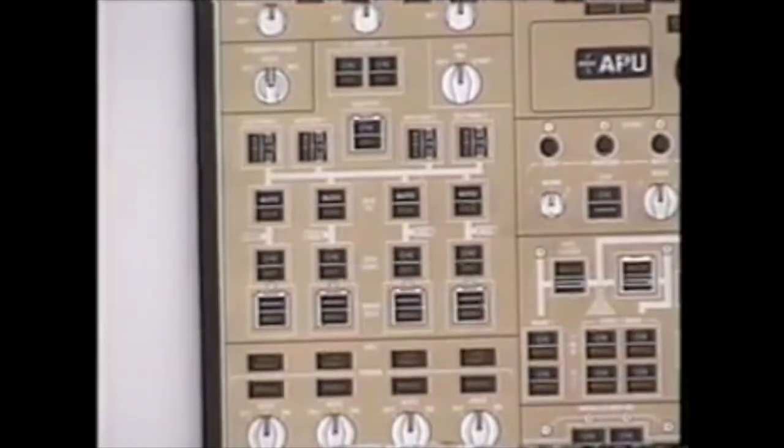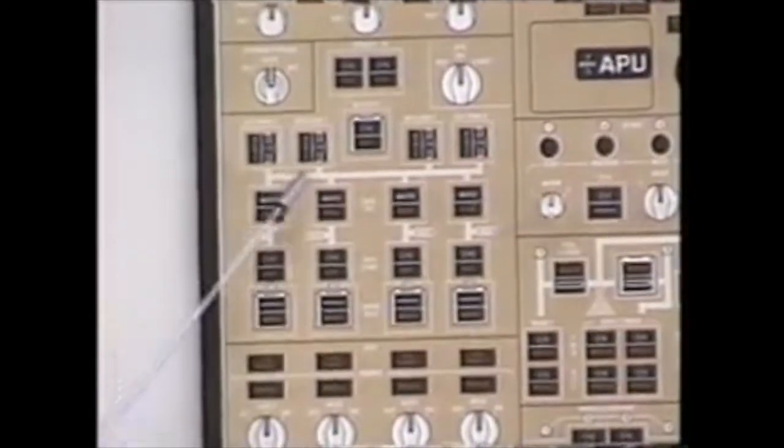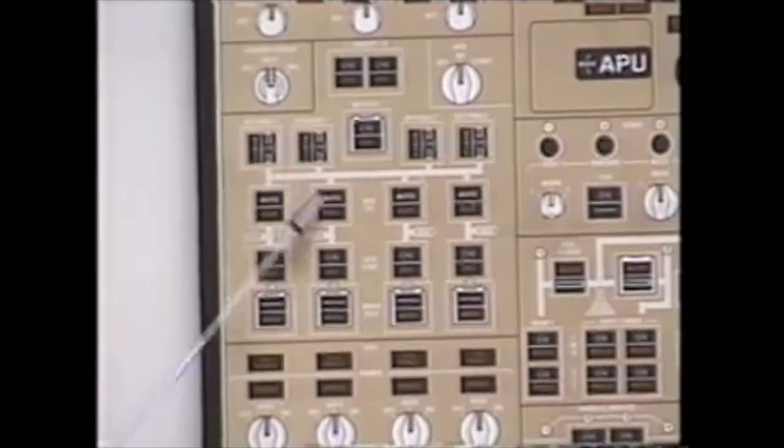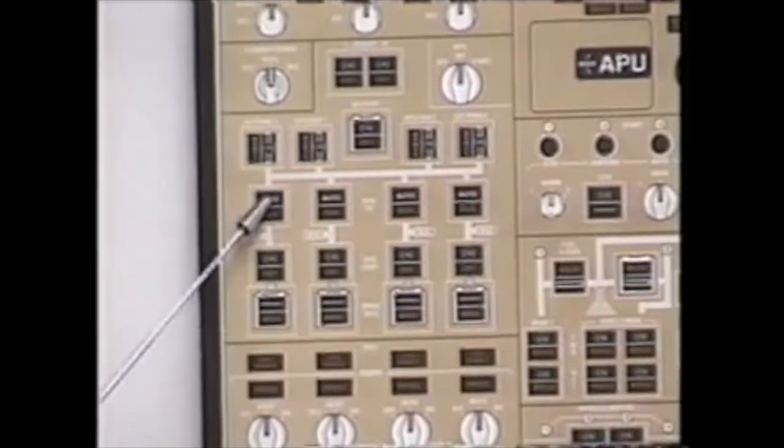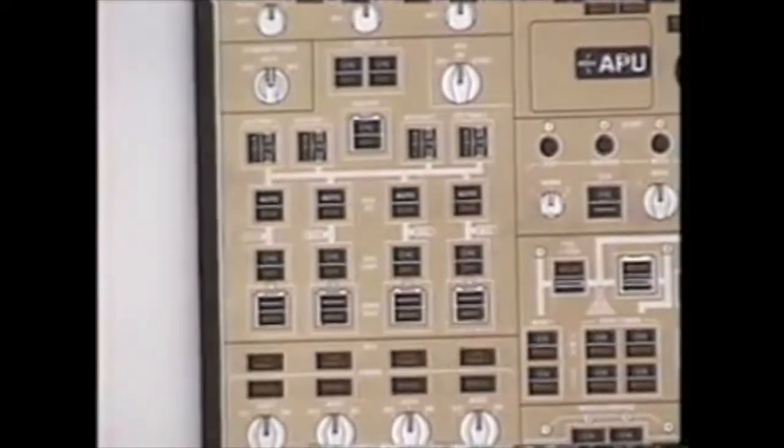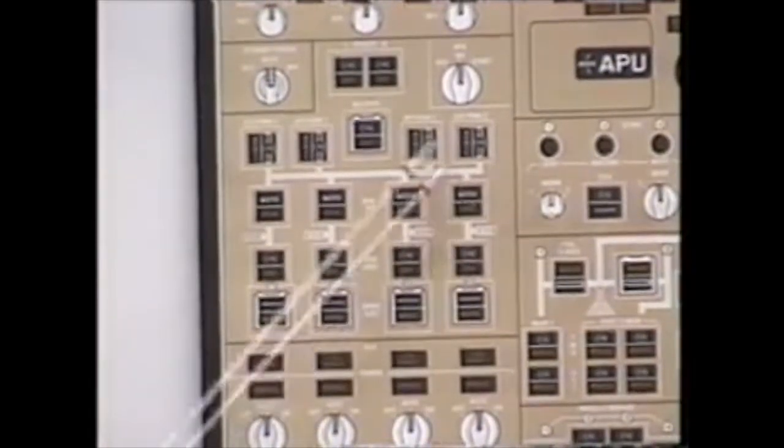Bus tie switches, auto and isolated. The airplane has the ability to isolate an AC or a DC bus and tell you about it on a primary ICAS. However, if you physically reach up and isolate a bus tie, you are opening both the AC and the DC buses. During a LAND 3 situation, the airplane will automatically isolate AC bus 3, AC bus 1, and AC bus 2 for the left, the center, and the right autopilot sterile sources. During that time, the panel will show auto, although the bus ties are truly isolated. The AC and DC tie buses will remain powered at that time through generator 4 in case generator 4 has to step in and pick up a faulty generator.